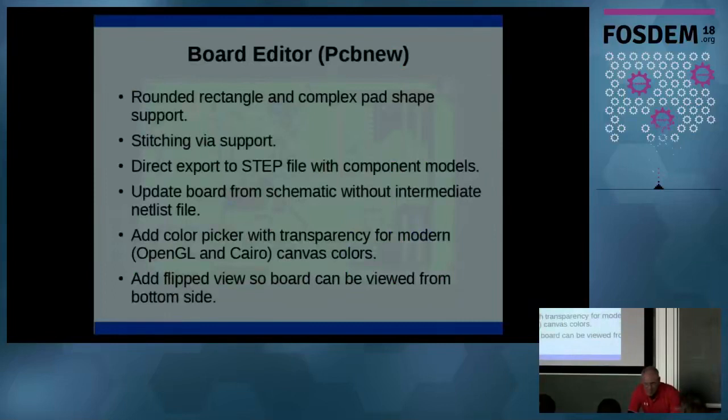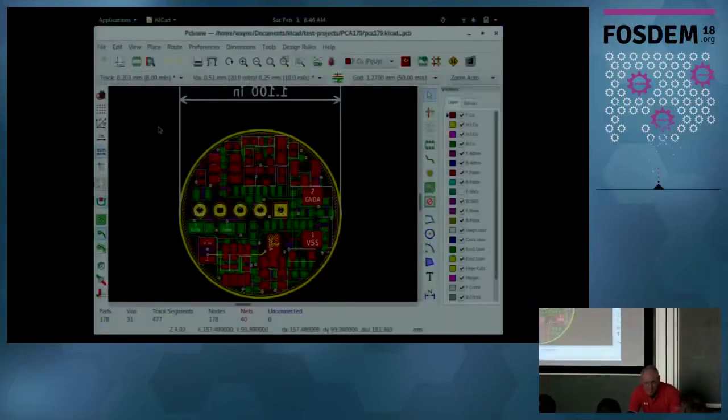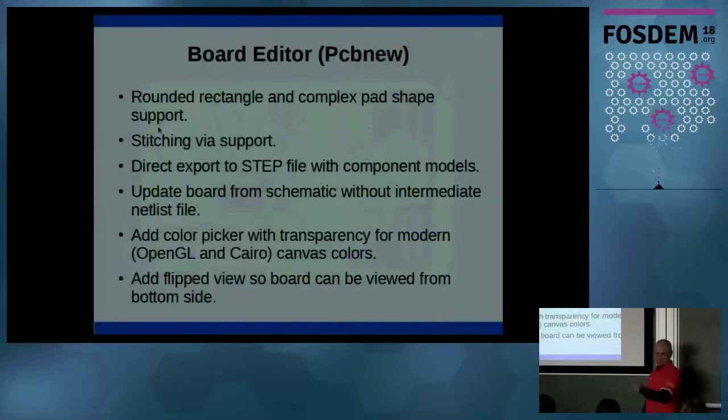One of the things that you'll find that's nice here that I'm not going to be able to show, because of the single view, is that we can now export directly to STEP file. In the past, it's been a third-party tool. We now do direct export to STEP. So when you export your board, if you have STEP models, it works one of two ways. You can either use STEP models in the board. So when you look at the 3D view,